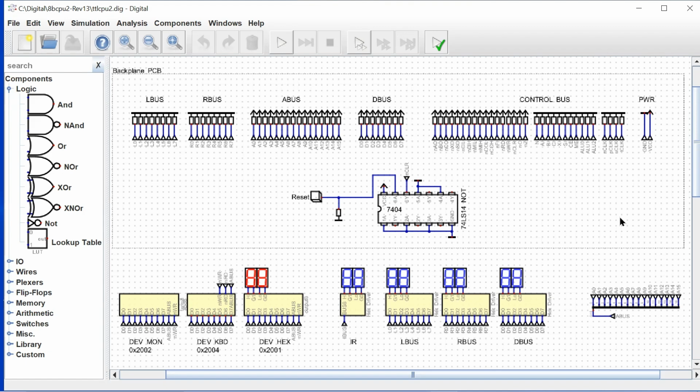It just makes a lot of sense to do the backplane last, after the individual boards are all tested and the designs are finalized, then bring the card edges into the backplane as our final integration testing. So that brings you up to date.